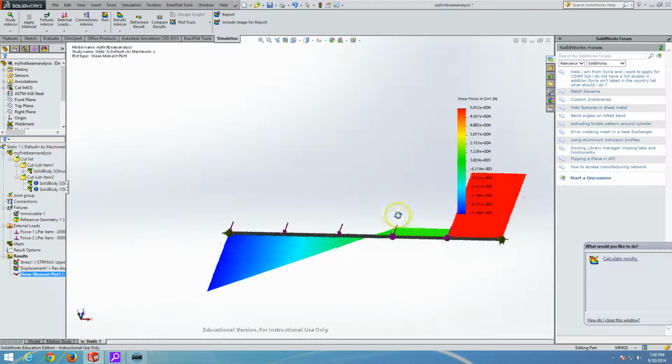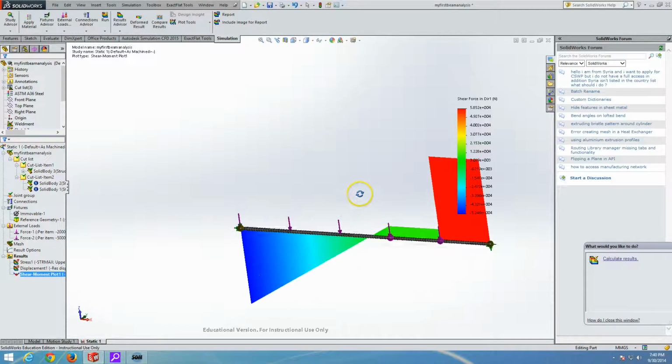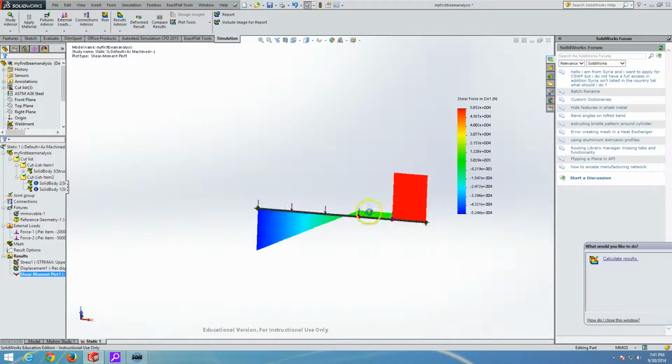Aha! And this looks pretty correct. Look at this. Here is the shear force diagram. So, those here at the end are what? They're our resistive forces. Those are the reactive forces from the ground, from the support. Here, it starts with whatever was your support, and you will have a position where the force will be zero. And the position where the force is zero, where it changed direction, is actually where it will break. Because that's where you have the maximum moment, maximum bending moment is here. And we will see that in a second on a moment diagram.